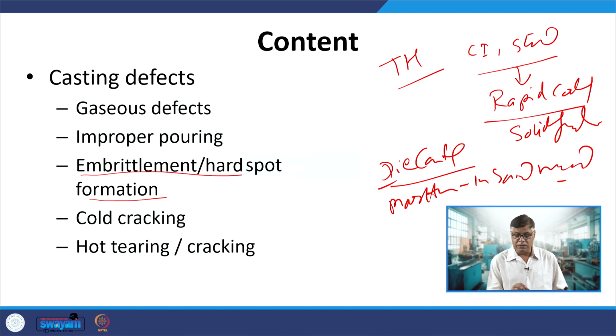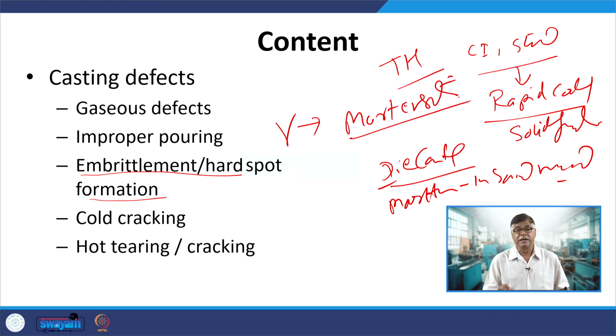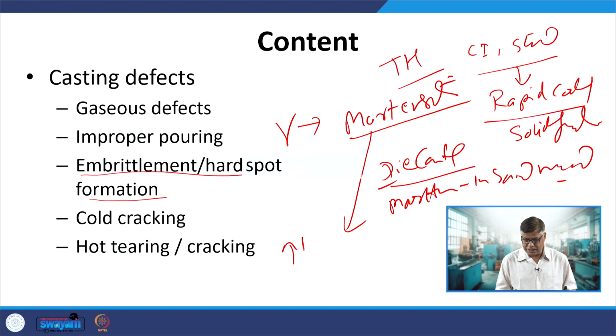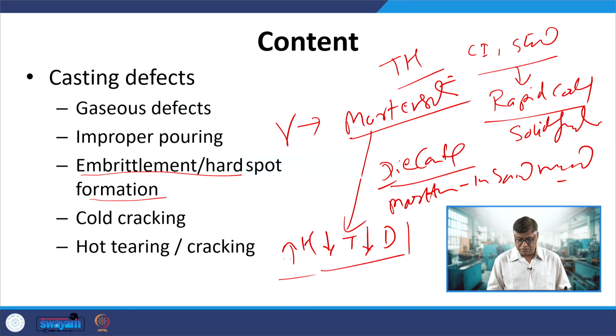So, what the rapid cooling does is, initially after the solidification, say if you are getting austenite, due to the rapid cooling it will form hard and brittle martensite, especially at the casting surface, or it can be formed all across the section. That formation of hard and brittle martensite leads to increased hardness, but coupled with reduced toughness and reduced ductility. So, these compromise very badly the capability to withstand impact loading.